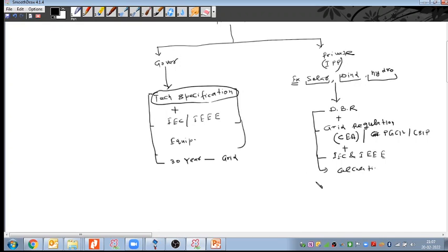I mean to say, if my solar power plant has 300 MVA capacity or 300 megawatt capacity, then considering this 300 megawatt, 300 MVA, we need to calculate the equipment rating, the equipment current ratings, and that is the only thing we have to fulfill. We do not need to go through what the next 30 years' requirement may be. This is the grid substation that connects into the grid, and that is the power plant or generating substation.